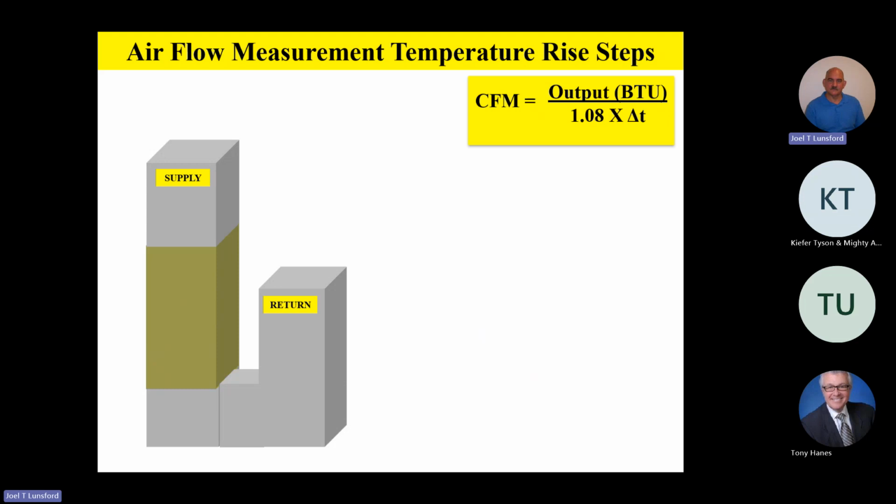Fellas, another method of measuring airflow, which has been around a long, long time, all it requires is a temperature probe, an amp probe, and a voltmeter. These are normal tools you'll find on any service truck: an amp probe, a voltmeter, and a temperature probe. And this is what we call the temperature rise method.